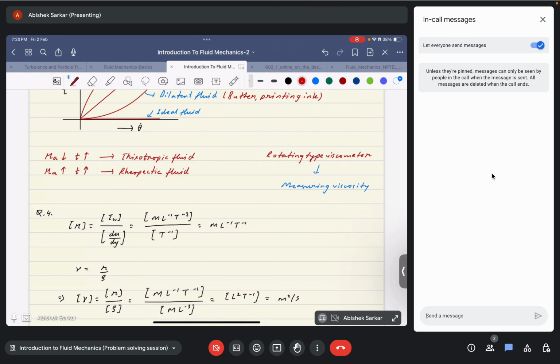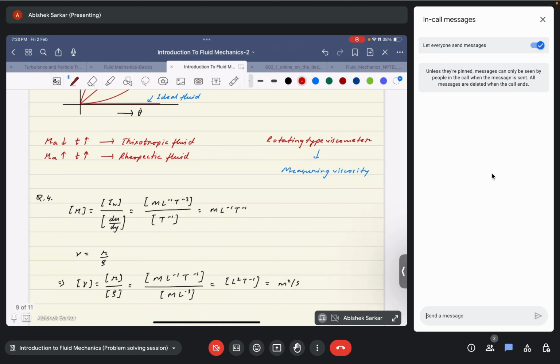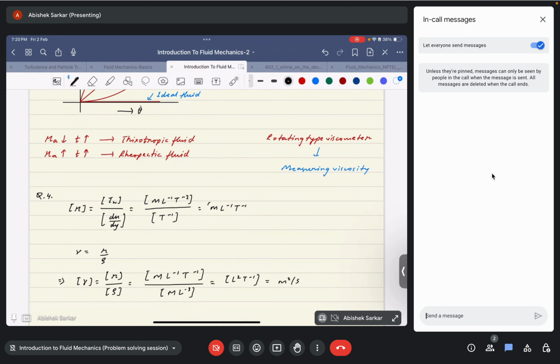Okay, I know it's very simple, but I just did a detailed derivation. I don't think it was even required, but still, for my part. We know that tau is mu du by dy for Newtonian fluids, and then mu would be equal to tau over du by dy. We just take the dimensions of each and every one of them.